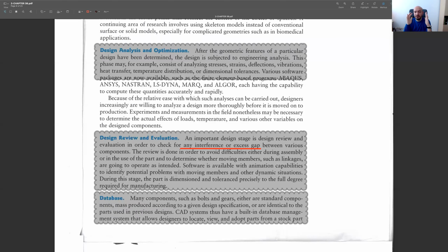You can perform some finite element analysis, check the stresses, and if you come to the conclusion that you have an extra amount of material, then you can remove material from some part, and then do the analysis once again and check whether the weight and the stresses are fine for your application. And this is a kind of optimization.